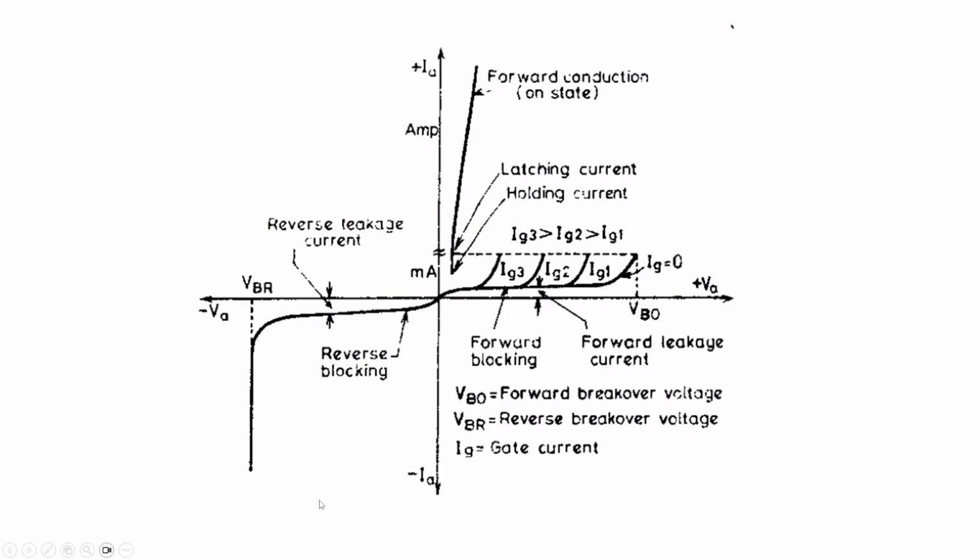Okay, so once the current through the thyristor goes below the holding current after gate pulse removal, okay, the change of current below the holding current can happen due to the natural commutation or the force commutation.